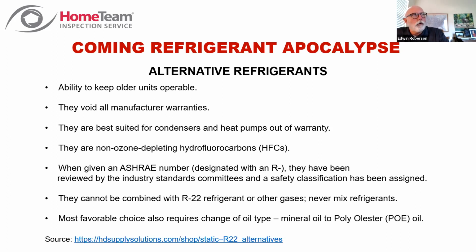And the refrigerant has oil in it, and that is primarily to lubricate the compressor as the refrigerant passes through. That's how you keep the compressor lubricated, by the oil that's mixed in with the refrigerant. And it requires an oil change. The R22 is mineral oil, and the alternative is the polyester. And there's a URL link to a website for some information there.